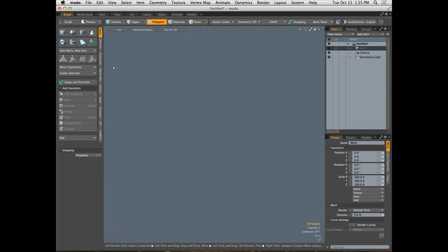Now, it is a toggle. It is an on or off thing, okay? So this is another big, big difference from that of other traditional 3D modeling applications. You either turn the snapping system all the way on or it's all the way off, okay? You can find the toggle for your snapping system right here in the interface, the big button that says snapping. This is just activating it and deactivating it, okay? The keyboard shortcut is the X key, X as in X-ray. So you have two different ways of turning it on. Just activate snapping, turn it off, or hitting the X key. I prefer to hit the big button up there at the top of the screen. I'm a mouse guy for the most part, so I like hitting the big button.